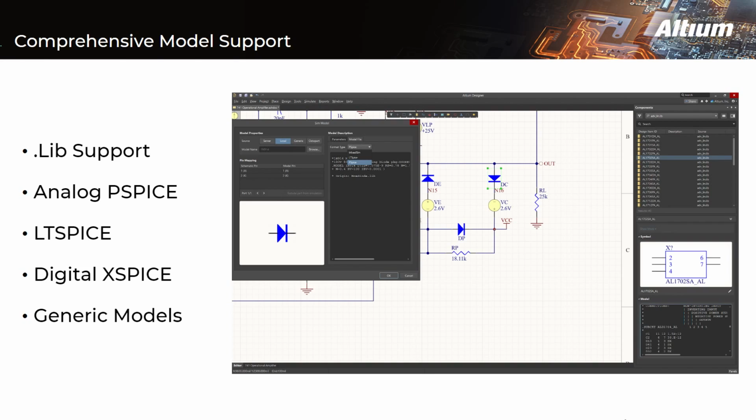The comprehensive Spice model support allows you to create unified component definitions directly in Altium Designer with minimal effort to link external models from vendors. So to start off, we have a new Spice Model Library extension, and it's called .lib. So .lib files are recognized as combined subcircuit models, allowing direct Spice Model Library file processing in the Components panel. You can also directly place Spice Model files, and an automatic component generation occurs.